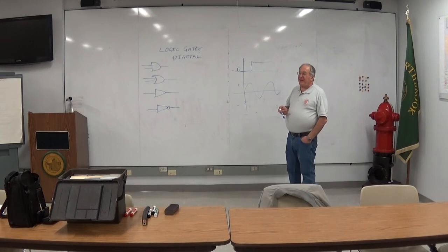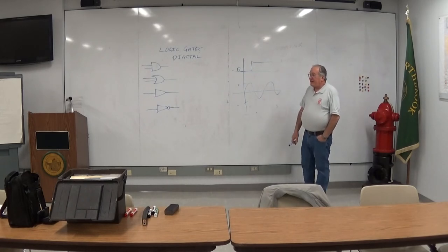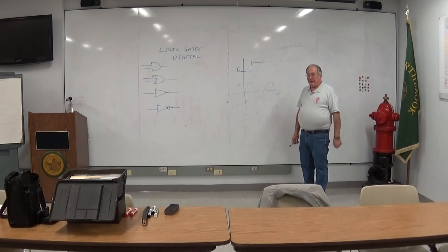In addition to the 3 active pins, the other pins were defined as things like clear to send, request to send, besides the 3 basic ones that were transmit, receive, and the common return. But the others were used to regulate traffic flow.